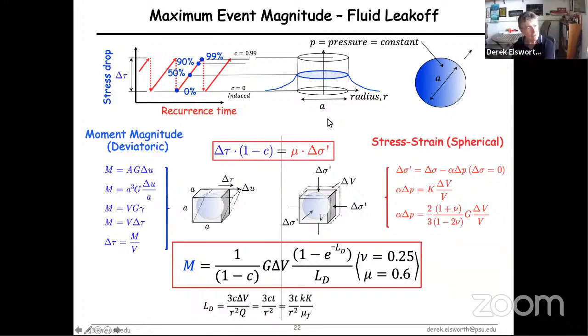Well, it's a bit like hydrofracking, but these ruptures that we were talking about for earthquakes are not in mode 1, they're in either mode 2 or mode 3. So the shear ruptures define the moment, but you can get similar behavior. Really what it's saying is that if you overstress the fracture, then you can fail it, and that rupture can either be constrained to the periphery of that pre-existing fracture, or it can extend beyond it in shear. The shear behavior, in mode 3 or mode 2, either one you can look at, goes beyond the existing pressurized contour.